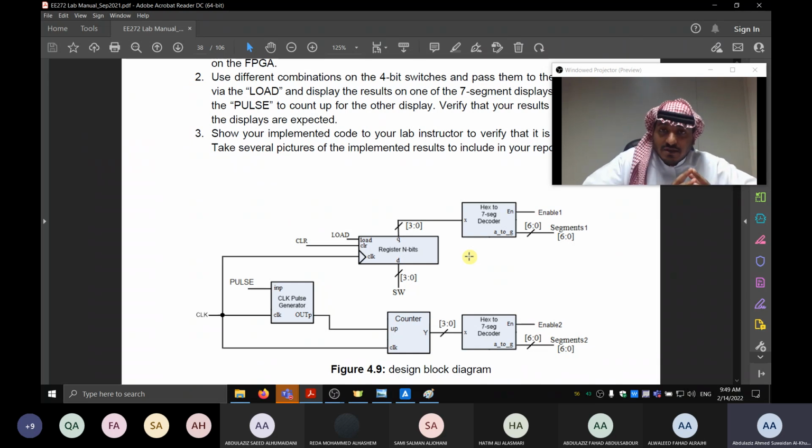So we're supposed to make this system work instead of using LED lights. All the past experiments we used LED lights for the outputs, right guys? Yes. Normally for the counter, there are 4 LED lights: 0, 0, 0, 0, then 0, 0, 0, 1, and when you count up it goes in binary up to 1, 1, 1, 1. The same thing with the register. If I make the switches 1, 1, 1, 1 and press the load, the 1, 1, 1, 1 is saved to the register. So that's one way, in binary. In general, it's a binary thing.